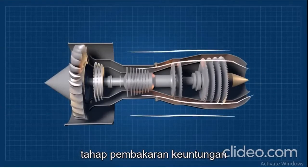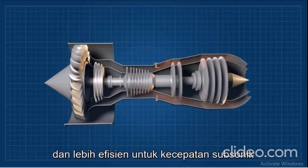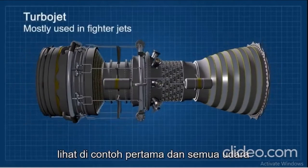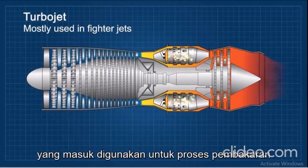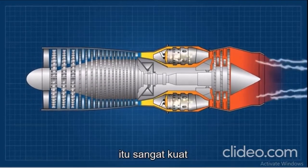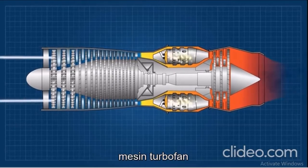The advantage of this kind of engine is that it's a lot quieter and more efficient for subsonic speeds. The turbojet engine is the one that we saw in the first example, and all the air that gets in is used for the combustion process. It's very powerful, very noisy, but somewhat smaller than the turbofan engine.